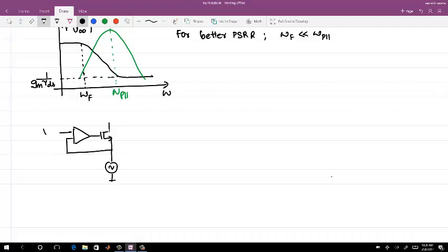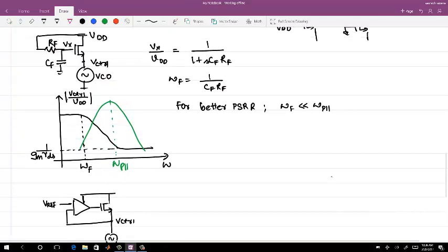So this is your Vref coming from the loop filter, and this is your V control. You can work out how it changes the time. What I have done is I just removed this part completely and did a simple one. The difference you would like to see here is that in this way you are actually getting a suppression at a higher frequency, no peaking in the response.